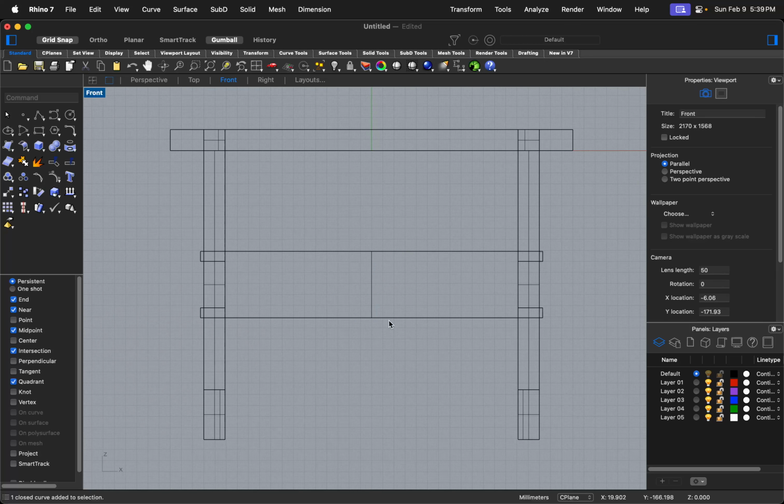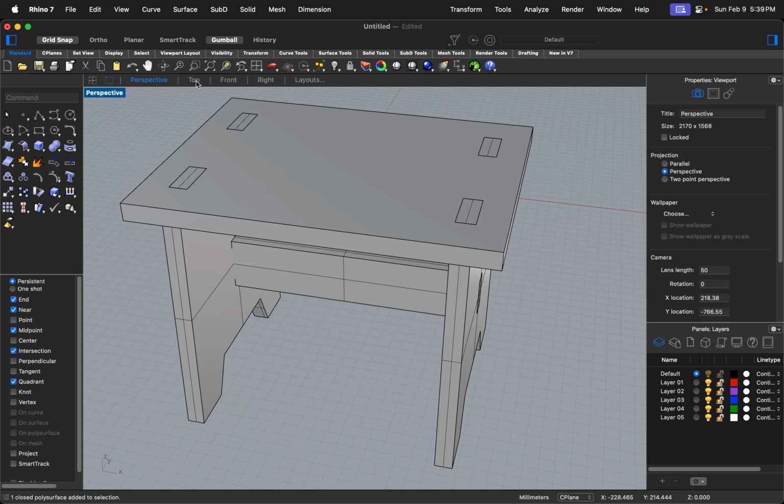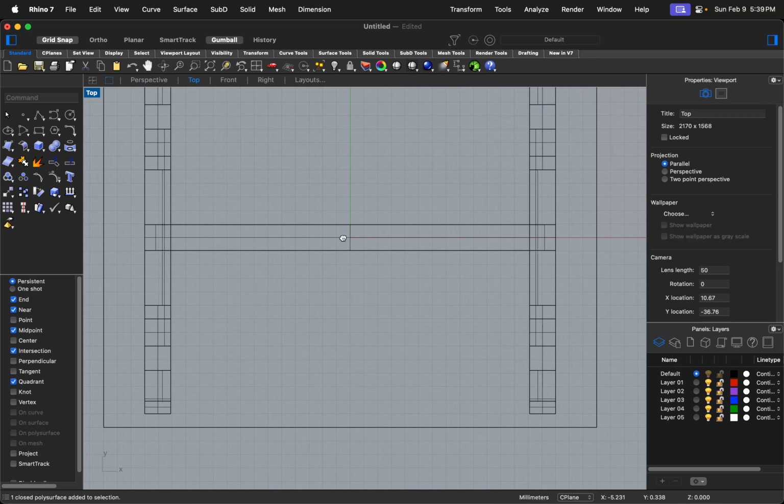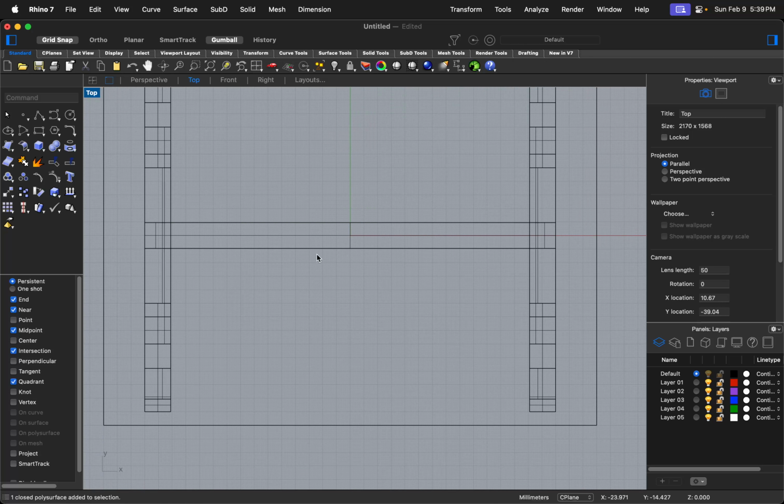Last but not least, before we do the final touch-up, let's look at the carrying hole at the top part here. As we have been using 19 mm for the overall thickness, I'll go to the top view and decide to cut something about 19 to 20 because that is the approximate size for the fingers. So to start the hole that we can fill up, let's create a box.